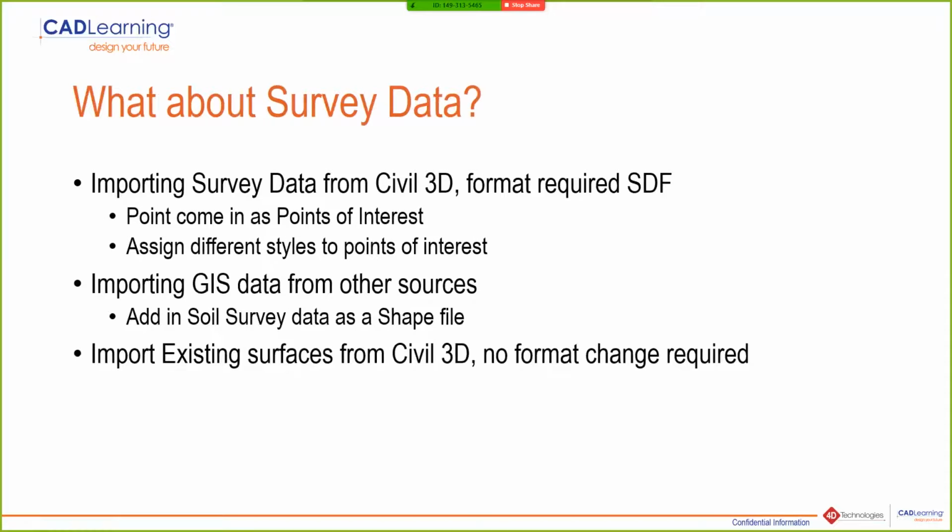Things you can import into InfraWorks. You can import survey data if it is in the right format. You can't import a text file or CSV file, okay? What you can do is take those and put them into, say, Civil 3D and convert them to SDF. SDF is an Autodesk format, and when it's in that format, it'll bring it right into InfraWorks 360, and you can assign a style to those points.